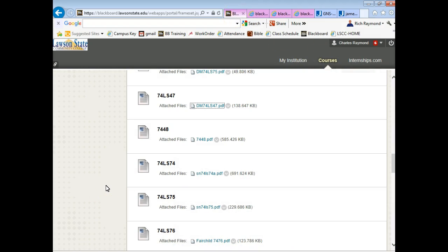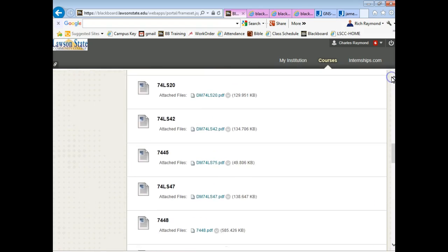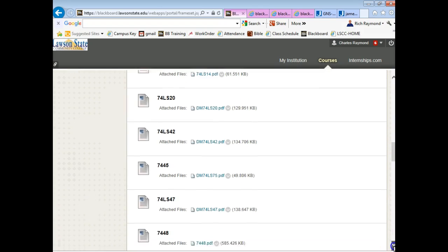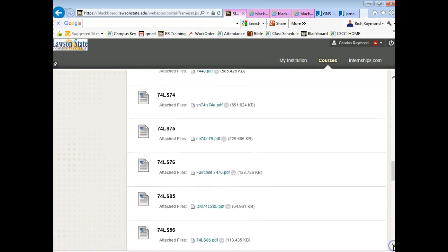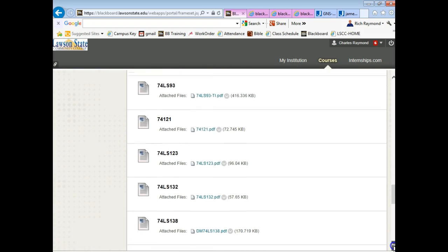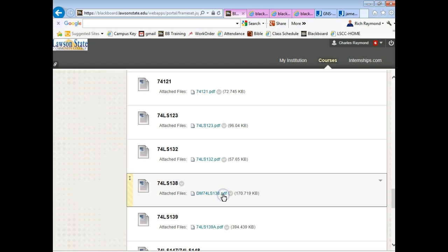So we have a 7442. This is a 4 to 10. We have a 74138, which adds a new feature that we've talked about several times, but now we'll actually see it in action. This guy here has enable and disable pins. We played around with AND gates, right? Using enable and disable, we understand how that works.